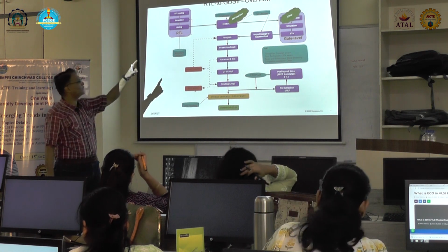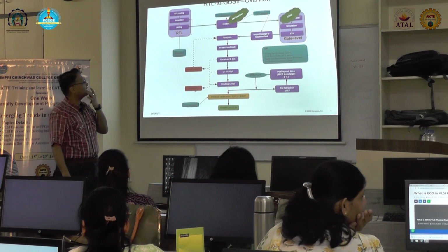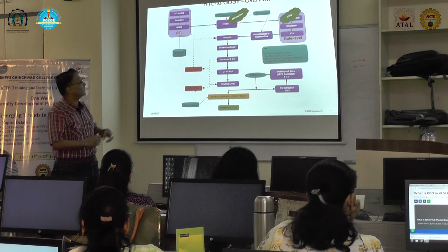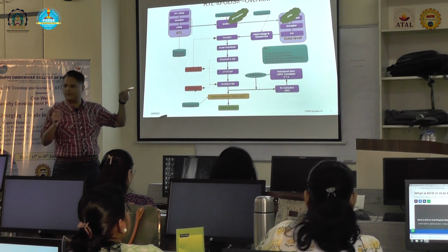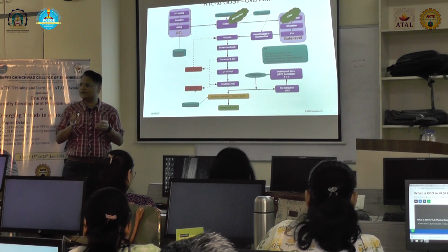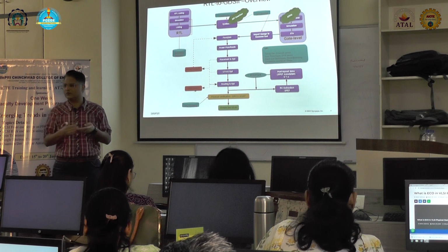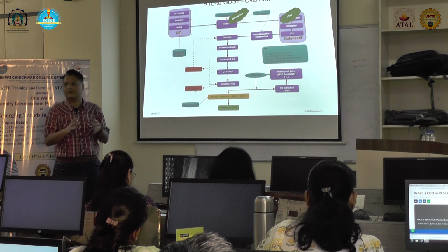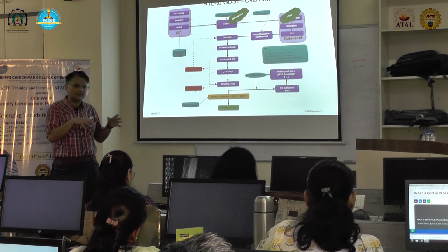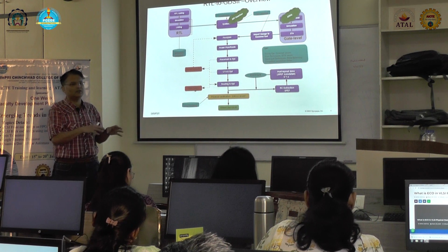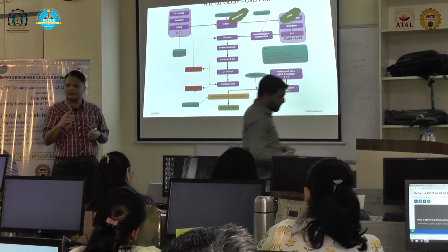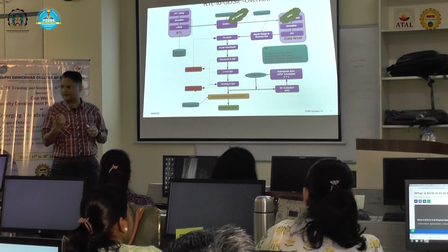Okay. Similarly, for DFT insertion, at the synthesis stage we have to enable it, but this requires additional circuitry. ATPG is something you just cannot do for free, so it has some cost associated. You have to add some additional logic into the design, which is called design for test. Typically we add some multiplexers.